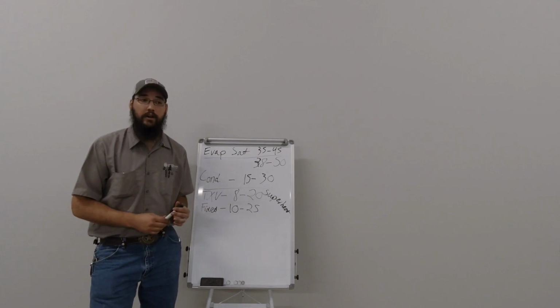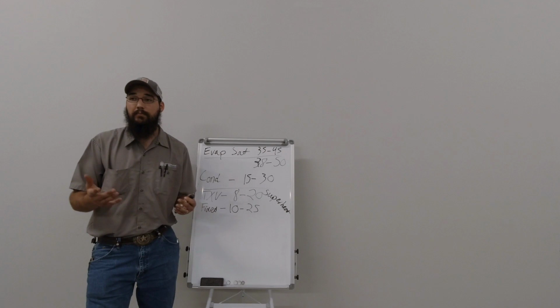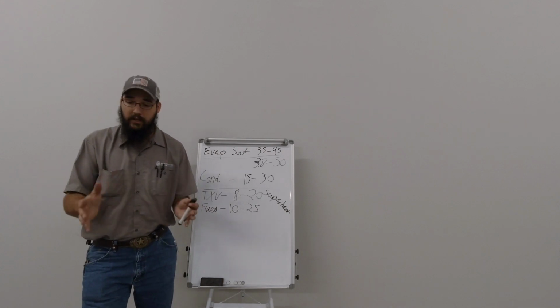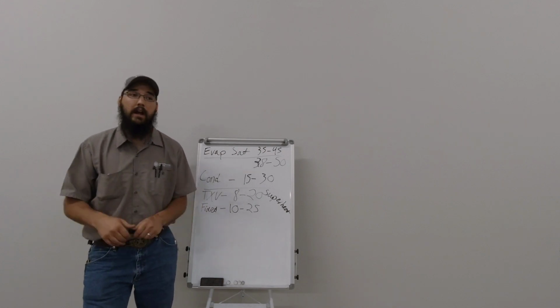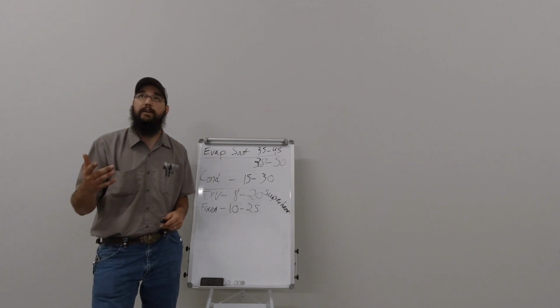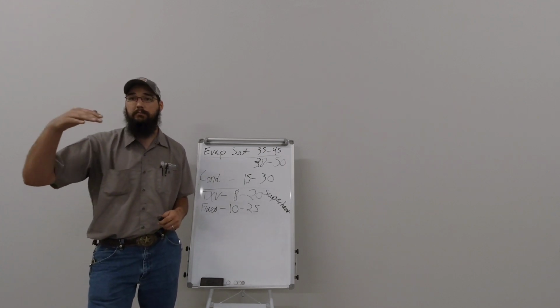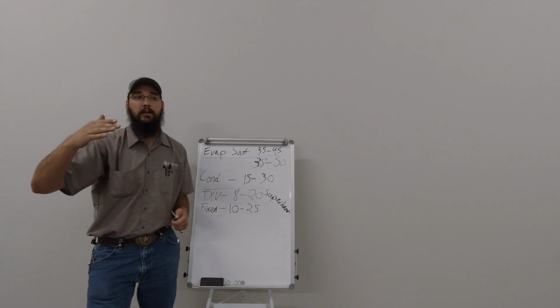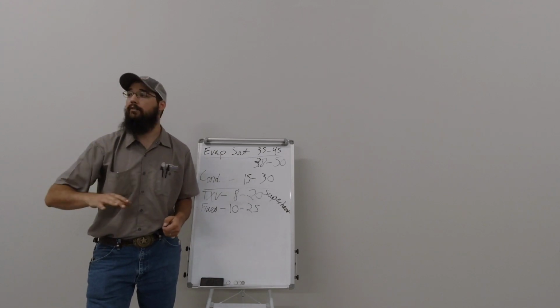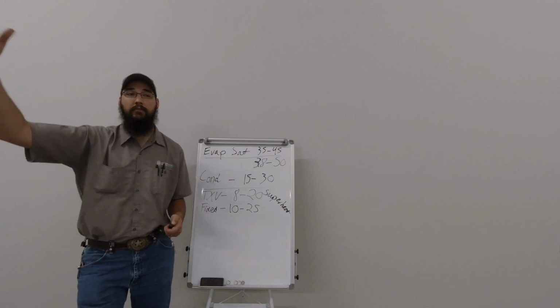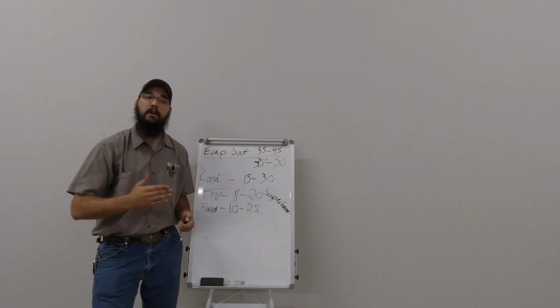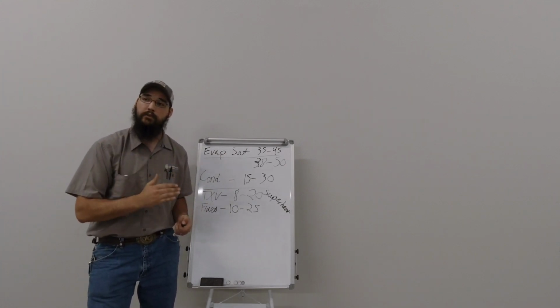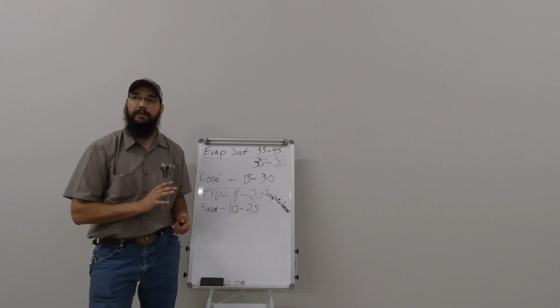Inevitably, in that particular scenario, what it ended up being is it ran by itself, just the one compressor, on the high end. It was about 25-ish. It wasn't all the way to 30, but it was in the 25-ish range by itself once it was said and done. But it gave enough buffer so that when compressor 2 came on, it was able to maintain about 12 degrees of superheat with both compressors.